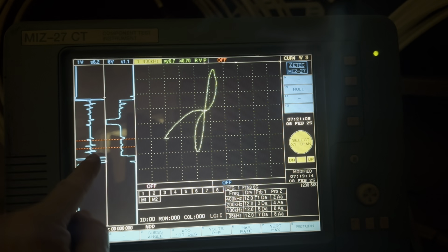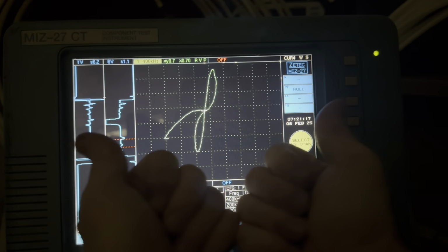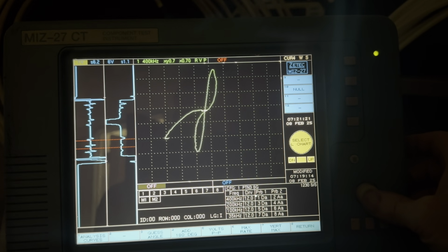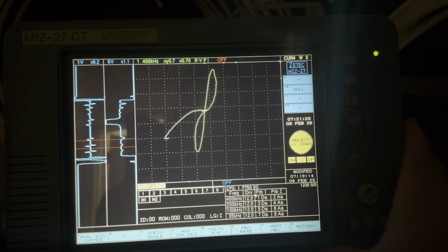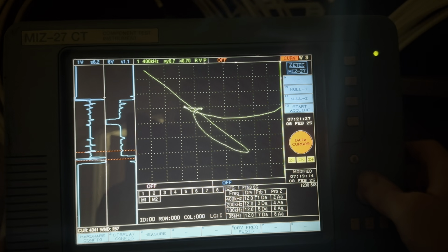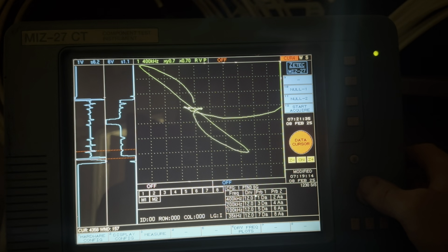What we're looking at on the left strip charts over here, the left one is channel 1 vertical. If you look on the bottom of the strip chart, you can see a deflection that goes down and back and up and back. So that's basically down and to the right on this particular signal. So I move below it with the cursor and then slowly go up into it. It starts down and to the right. Down and to the right, goes up and then back to null as the coil pair moves past the flaw.